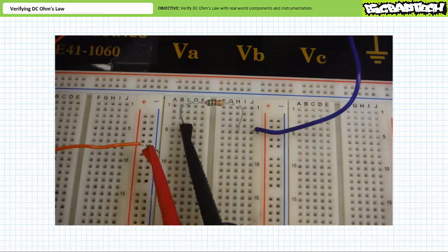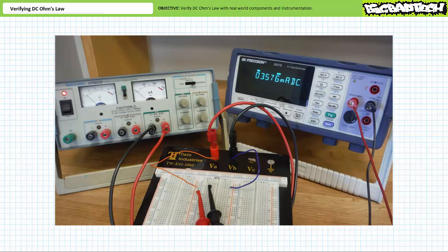A complete circuit has been established and all current must pass through the ammeter. When we power on the power supply, the ammeter displays current through this circuit, and thus power dissipated by it is consistent with our theoretical calculations. We now need to repeat these observations in 2-volt increments up to 12 volts.